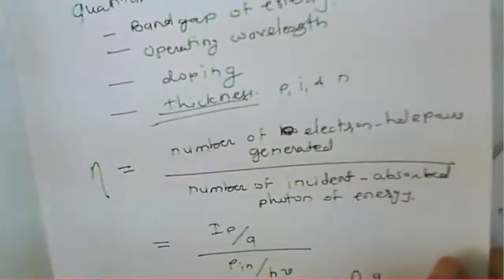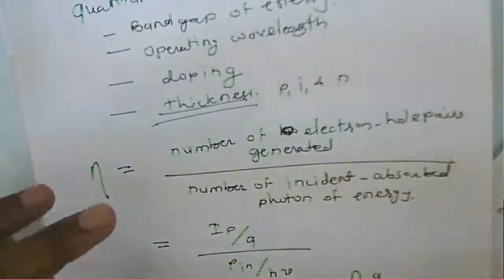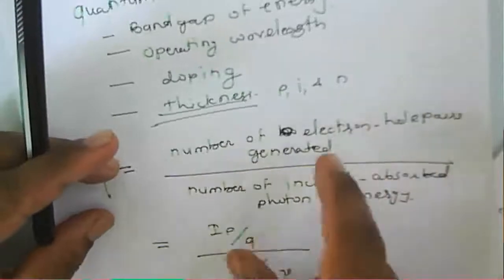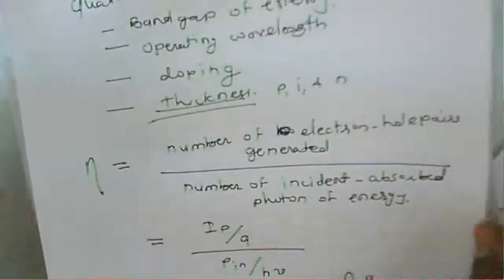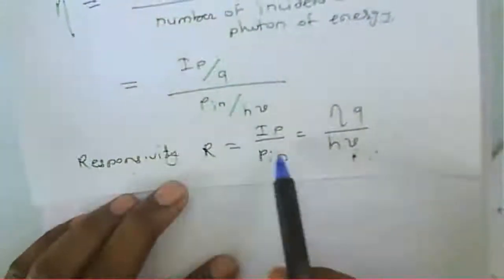So for a given particular material, we should know what the incident wavelength must be to generate photons of sufficient energy, or to generate the number of electron and hole pairs. That's why responsivity and quantum efficiency both depend on the material and on the cutoff wavelength. The cutoff wavelength is different for different materials.